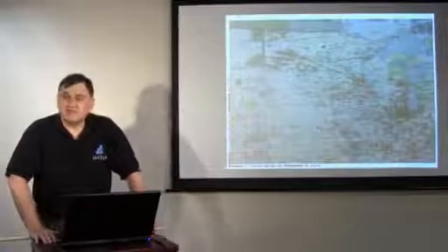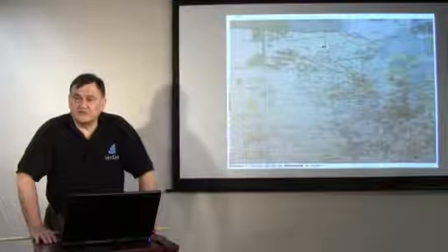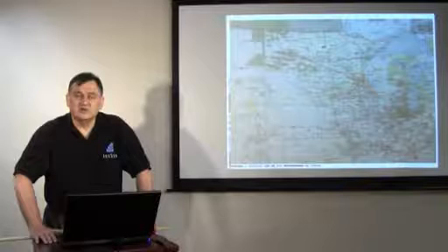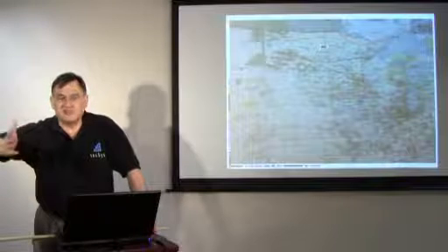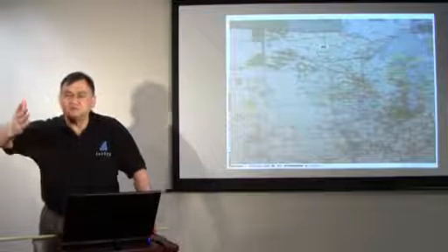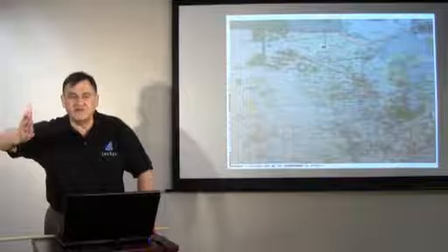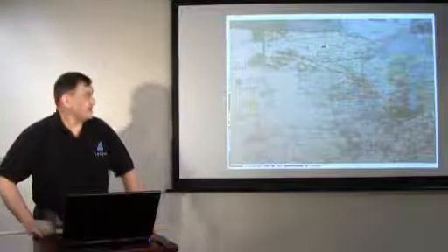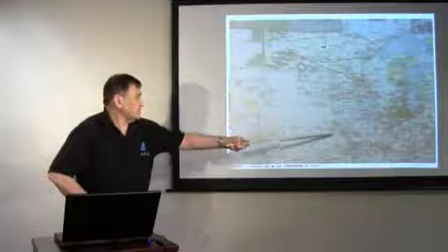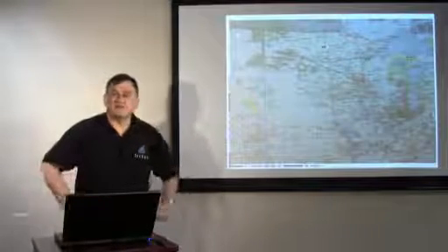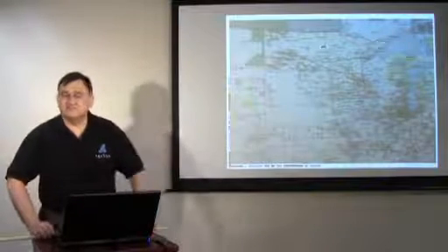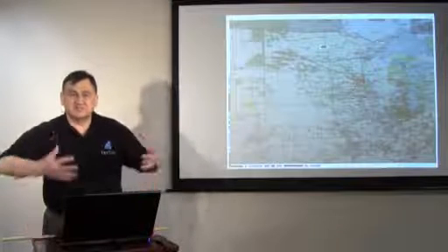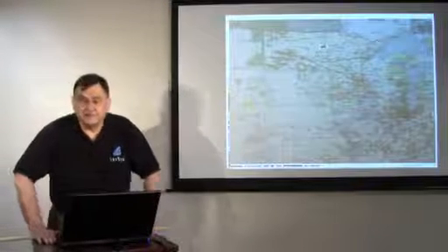Now, we're not seeing a lot of new transmission lines going in the eastern part of the interconnection because it's clearly much more congested. What you're seeing in the east is transmission voltage upgrades. They'll take maybe a 138 kV line and upgrade it on the same right-of-way to 230. But clearly, in the western and the Midwest, there's a lot more open spaces, and you're seeing some very ambitious plans to put in very high voltage transmission lines to connect the system much more closely together.